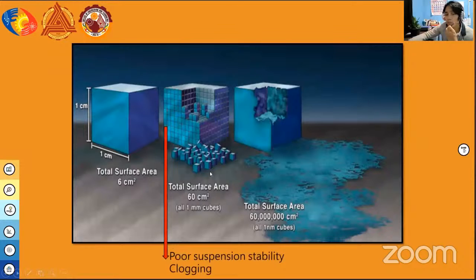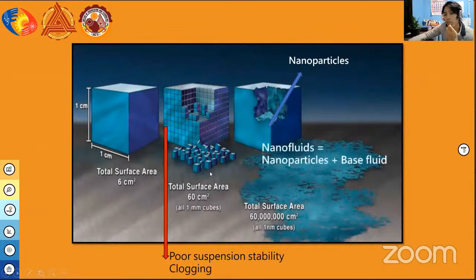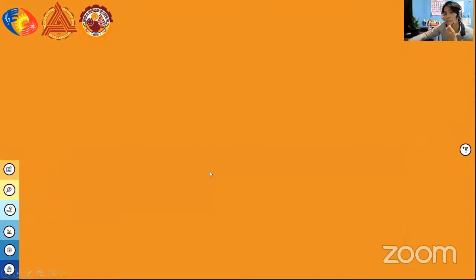With the recent advances in material technology, it became possible to produce innovative heat transfer fluids by suspending nanometer sized particles that change the transport and thermal properties in base fluids. Solid-liquid composite materials consisting of solid nanoparticles with size not larger than 100 nanometers suspended in liquid are defined as nanofluids. Nanoparticles showed better suspension stability for they offered greater surface area per mass. As the surface area per mass of a material increases, a greater amount of the material can come into contact with the surrounding materials, thus affecting reactivity.